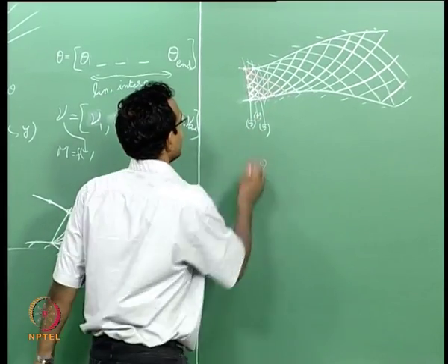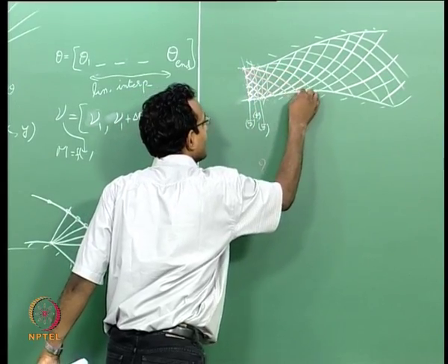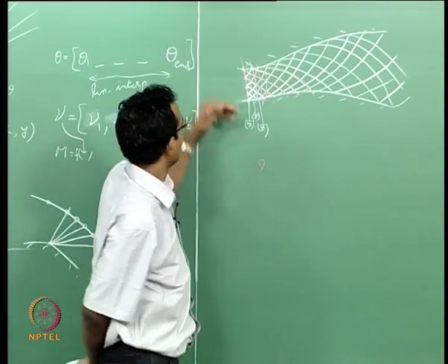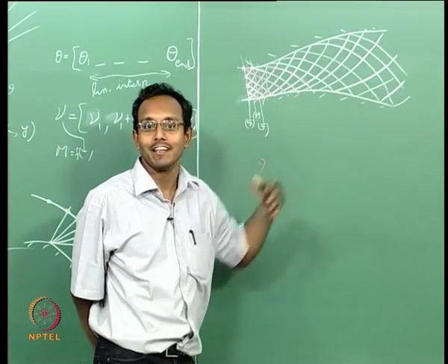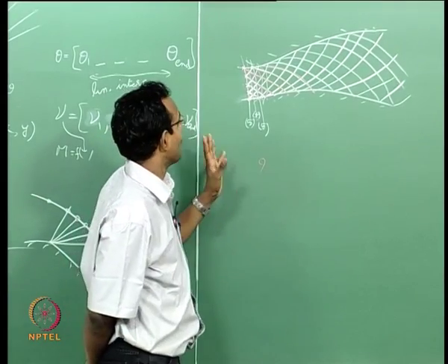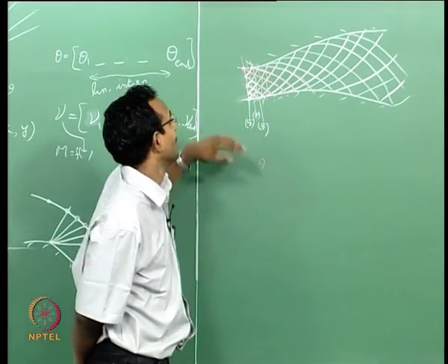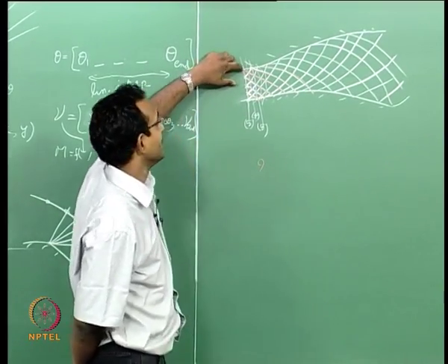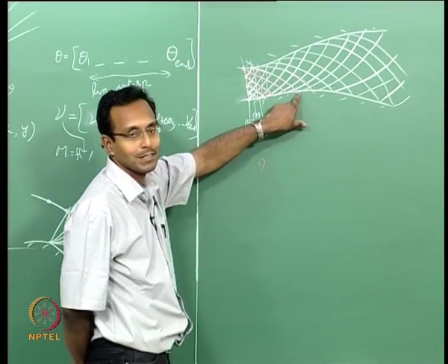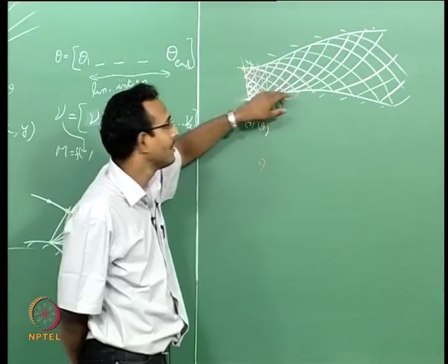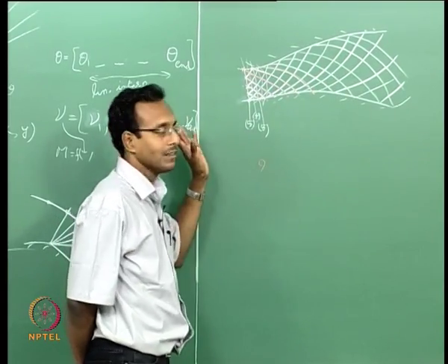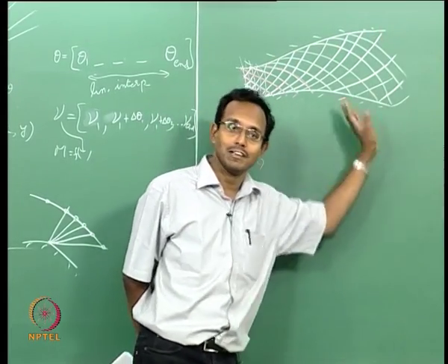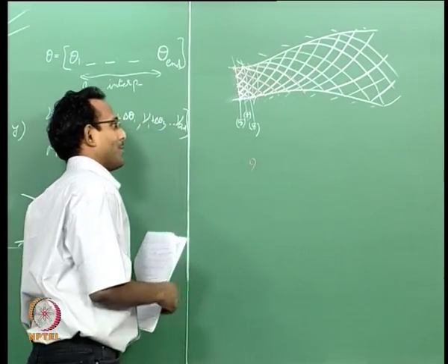After that, if I start solving only along negative characteristics, there is always the same number of points, so it is easier to store it in a nice array. And plotting also becomes easier if you start thinking this way. I will just solve it like this. From here again you can notice that it is 9 points. Why? I am losing the topmost point, I am introducing a new point at the bottom by creating one wall point. This is the way I will be solving this whole thing. Now there will always be 9 points, 9 points, 9 points till the end. There is only one small problem.